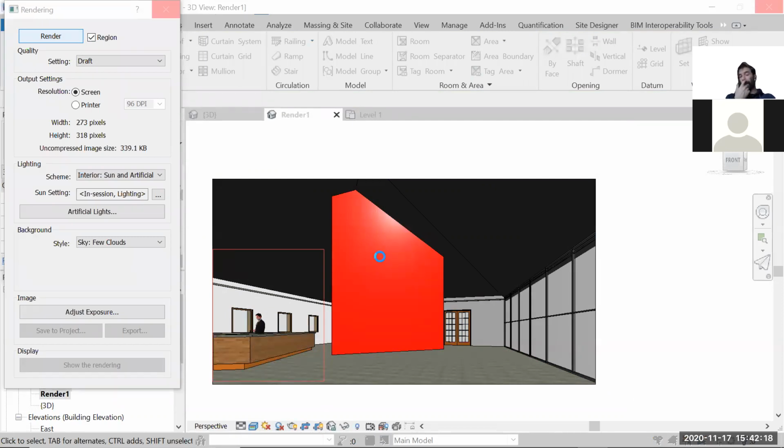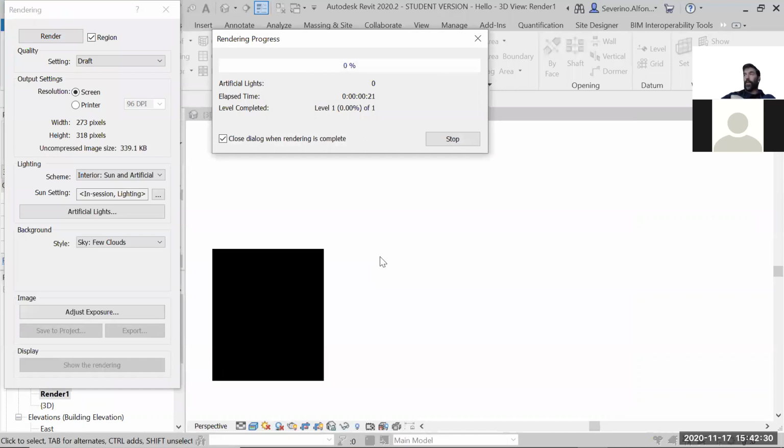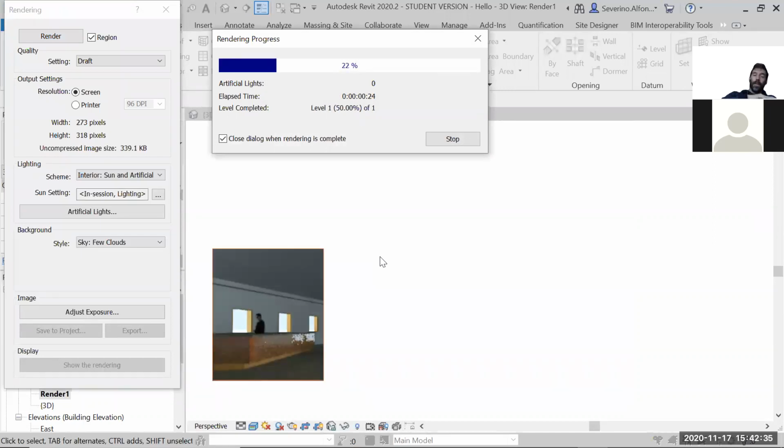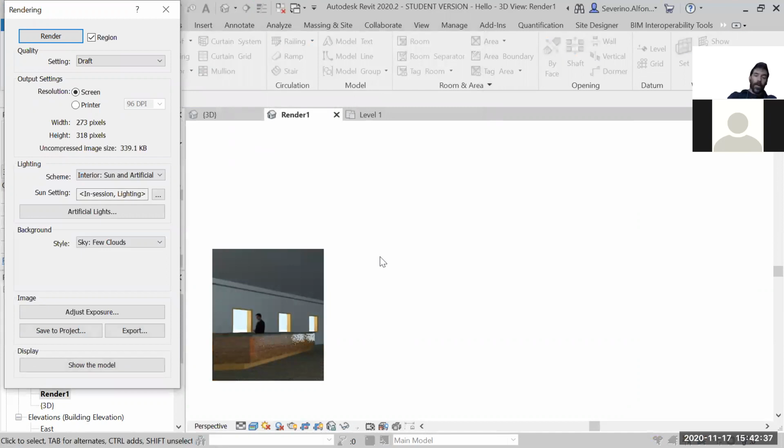So extrusions are quite straightforward. I recommend that you think of one piece of furniture as possibly having many extrusions and other elements to it, but don't do one extrusion, finish, and then do another model in place to do another extrusion that relates to that same model. You want to complete the whole, let's call it counter, with as many tools as you need, and then say, I'm good with that, no?